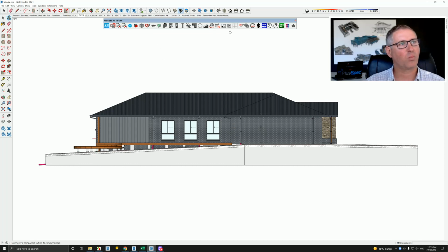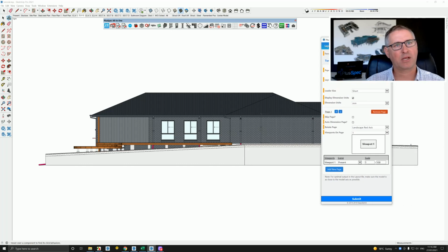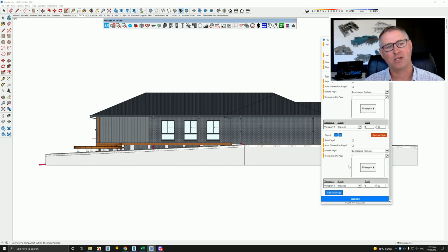And it could be a building application, or it could be a development application or development approval. And essentially the way we would do that is we would use a construction document set. So we could choose a paper size, so we might say A3 paper size. We could choose a template, which might have all of our headers and information. We could choose whether it's going to have dimensions inside of it, and we could choose what we wanted to have on each page. So we might say on the next page I wanted to have my elevation, and we might have multiple elevations on a page, so we might say 2 elevations on a page, and then we can create some construction documentation that we can utilize for submission. We can also give it to builders on site who don't have access to the 3D model.